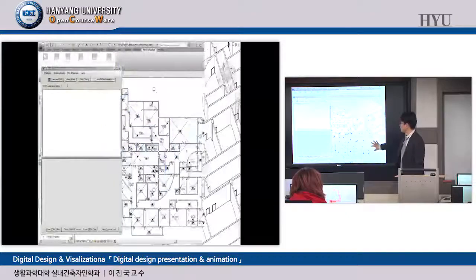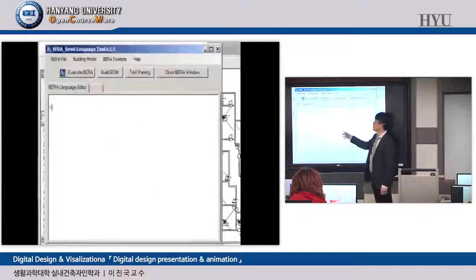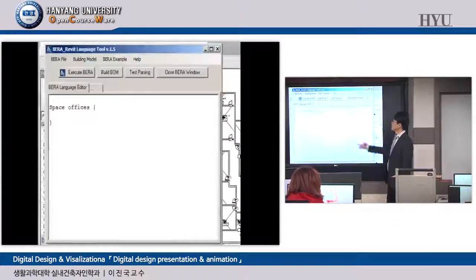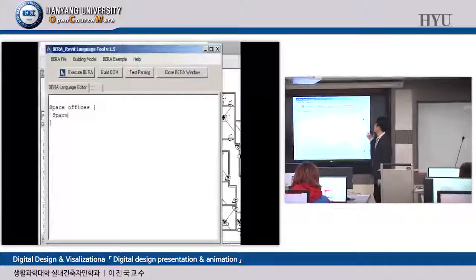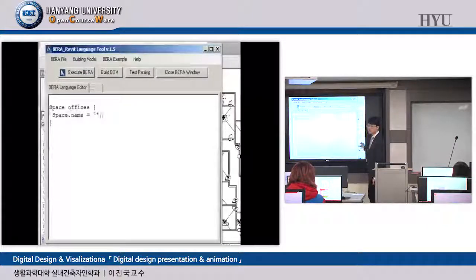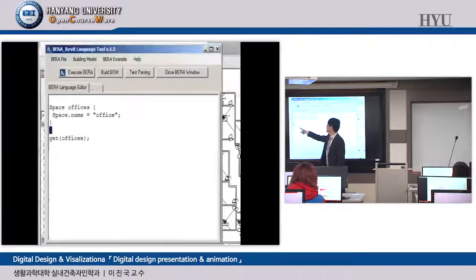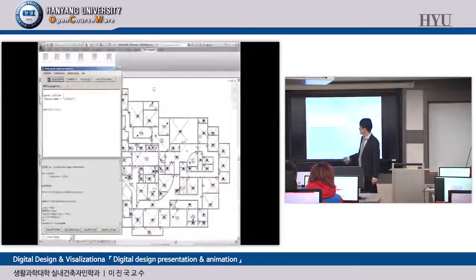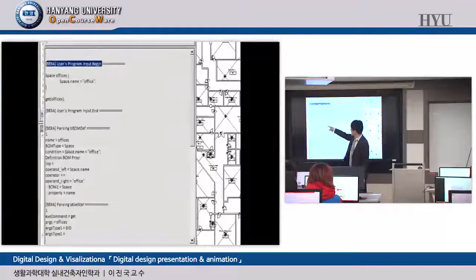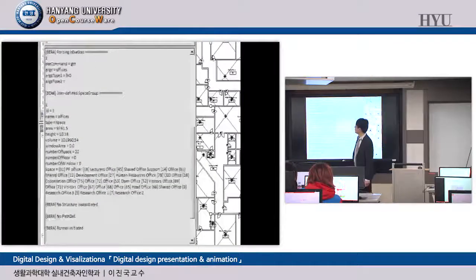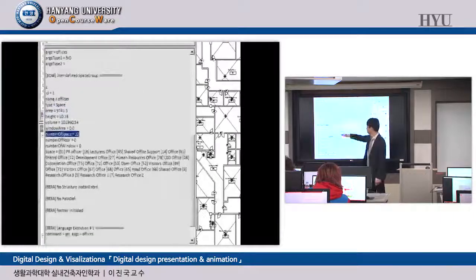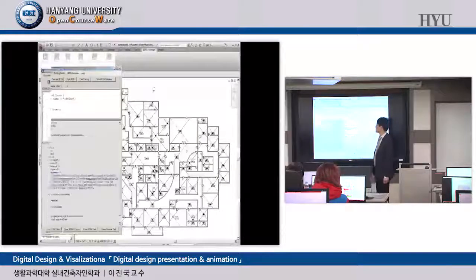This is a Revit model, okay? And some type of language querying structure. This one is possible. Simply, this is a BIM model. If this is a Sketchup model, 3D Max model, or Rhino model, this is not possible. Now I'm going to choose the entire office spaces in this building, okay? And then the total offices found in this model. You can take a look here. Total 22 office spaces selected, and we can review them one by one like this.